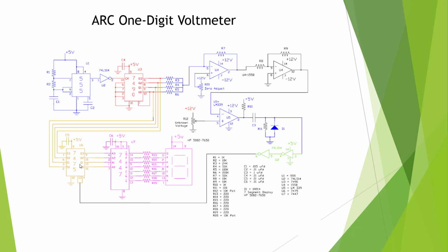So we're going to lock in that number in digital and binary, and we're going to convert that binary number to a 7-segment display based on the 7447. All these components we've used already, and we will get a chance to look at them more closely.